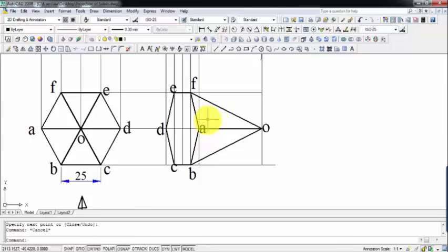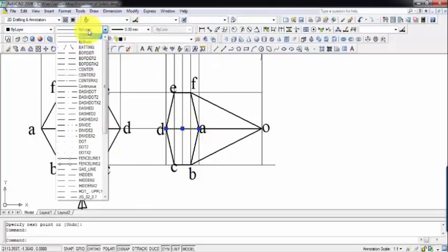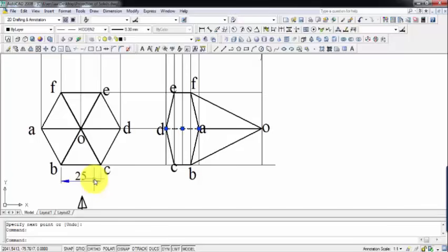Okay, now there are a few slant edges which will not be visible in fact. So please watch this carefully. There is going to be a slant edge from T to O. Okay, and for that, only this much portion is visible, and for the rest I'm going to use a hidden line. So this is going to be your hidden line.